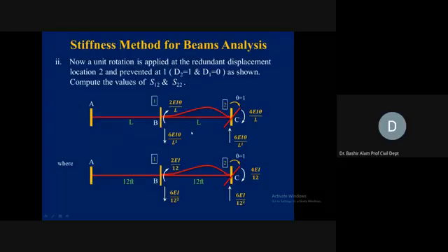Now to apply this to our actual problem, here 4 EI theta, with theta as 1, divided by L, L is this 12 feet, so 4 EI divided by 12. To the far end 2 EI divided by 12, and balancing couple 6 EI divided by 12 square and 6 EI divided by 12 square. Now looking for the corresponding values.